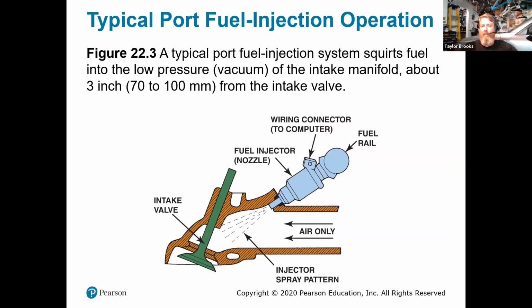The benefit is that, depending on how the injectors are timed, whether sequential or non-sequential, we're able to spray just the right amount of fuel. We also don't have fuel deposits stuck to the intake manifold, although we will in cases with an open plenum, where there is some reverberation pressure going back the other way in the intake manifold to the next cylinder that is going down on the intake stroke.